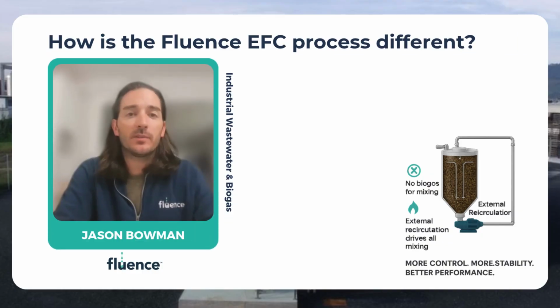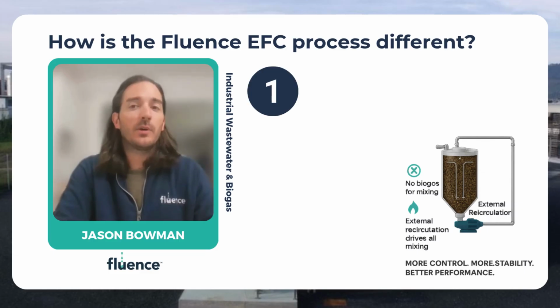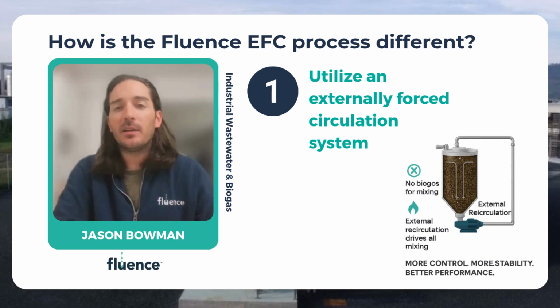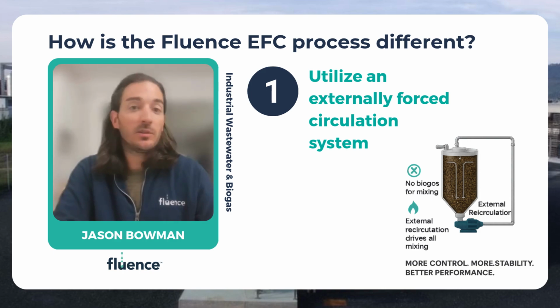So how is the Fluence EFC high rate process different? Well, we really have three distinct design features in the EFC process. First and foremost, the most important is the fact that we utilize an externally forced circulation system, hence the acronym EFC. Many other high rate systems actually use biogas to aid in the mixing of the granules.